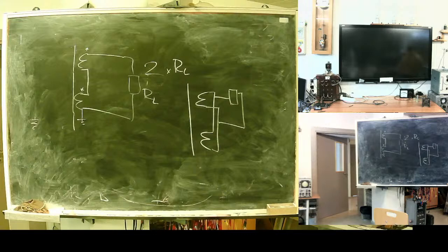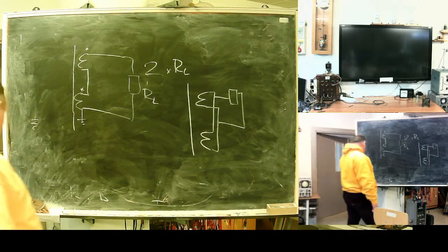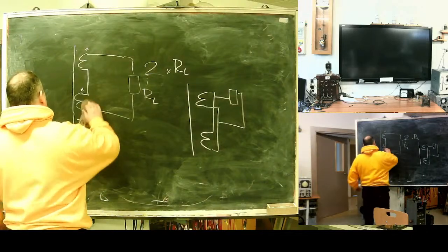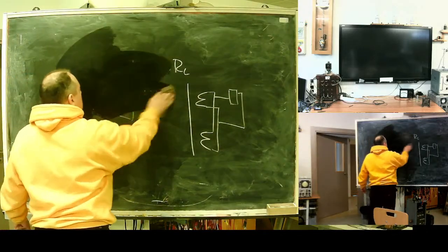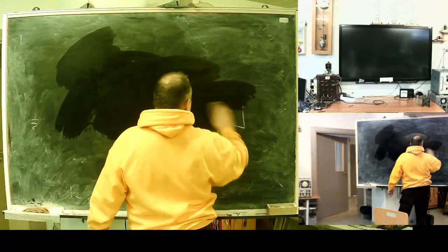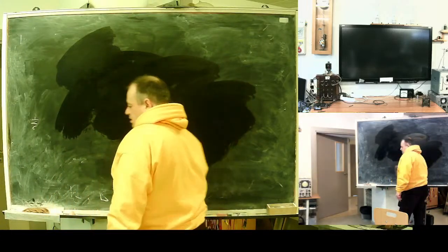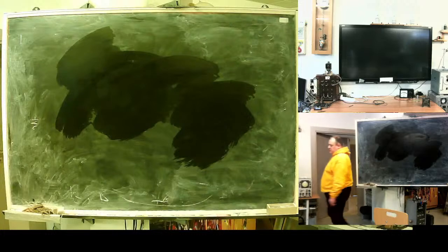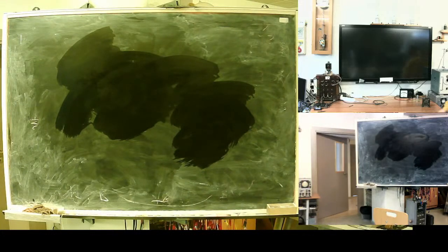If you open it, you can find 3, 4, sometimes even 6 current transformers inside, flat like donuts. So you will have spare current transformers, and in case you need to increase load capacity, you can use them.